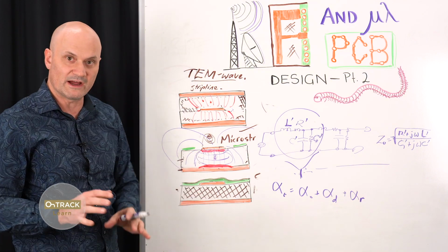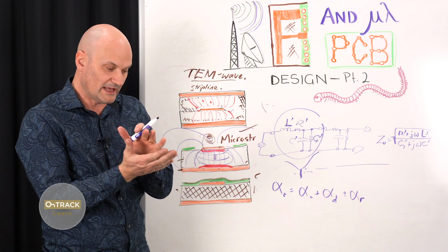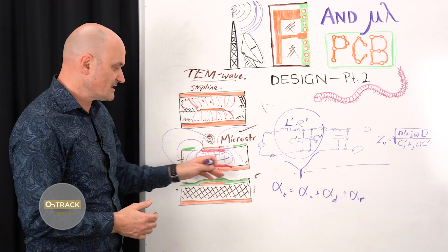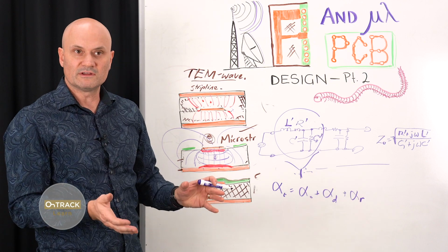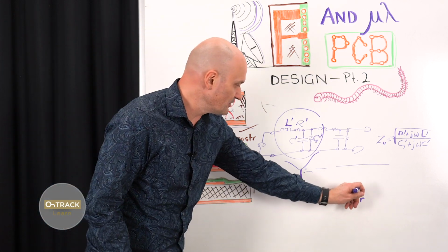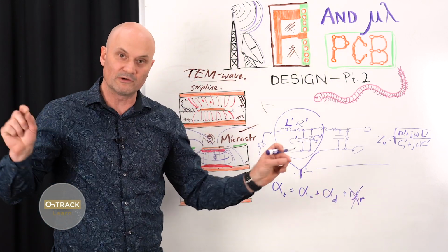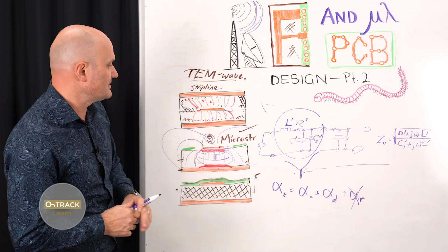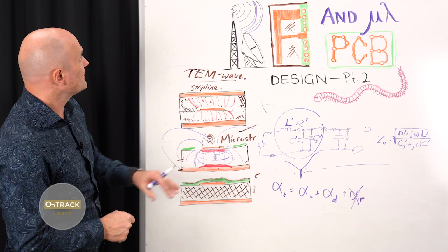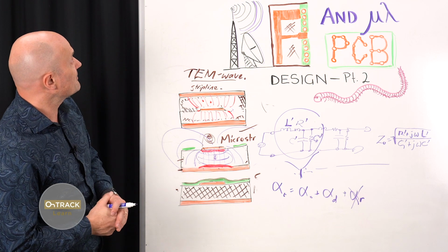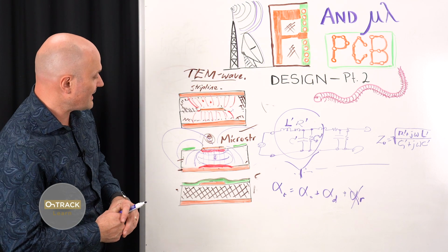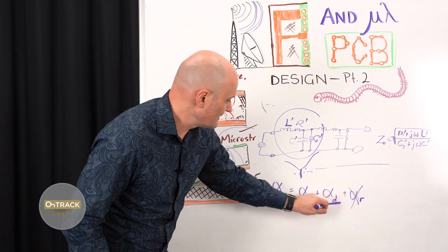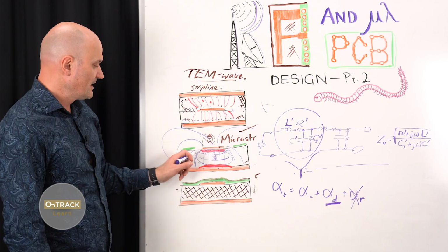If you design this right and you have close coupling of the plane and the trace, most of the energy is contained in here, and you don't have to pay too much attention to this if you're not going a long distance, right? But there are radiative losses as well. So how are these sorts of things derived? Let's just look first at dielectric loss, because this is the one that's harder to sort of figure out.